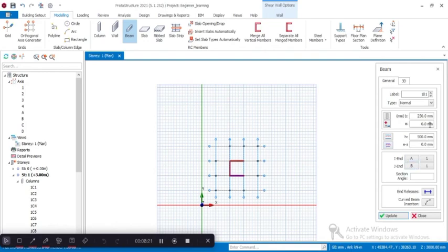The E is still 0. Then this shows two hinge joints, one hinge joint, simply supported beam. So you can change to curved beam. We'll be seeing all that. And type of beam: supported beam, wall beam, coupling beam. But we are using normal for now. Beam endpoints: beam ends are fixed. So these are fixed joints. Beam ends are fixed by default. You can apply hinges to left or right by clicking successively on this icon, as you saw me do.